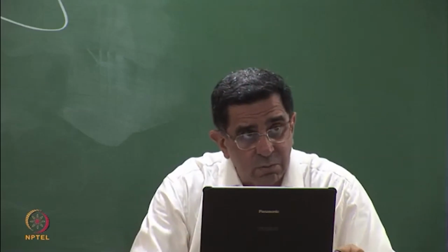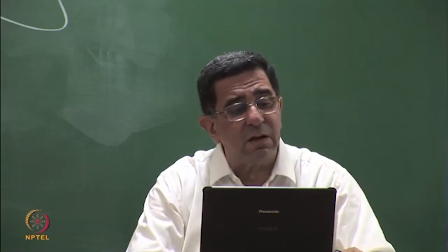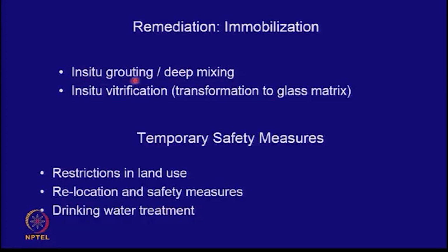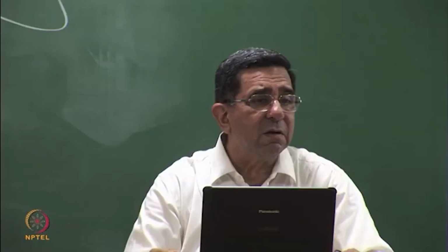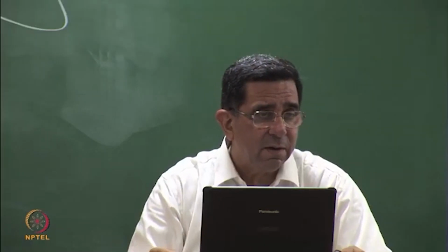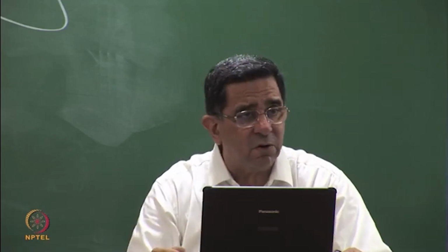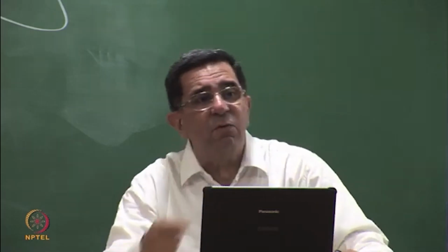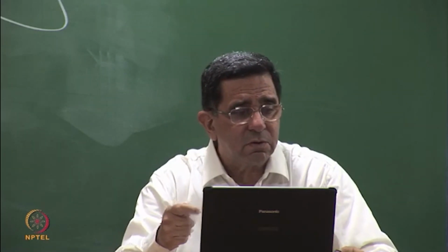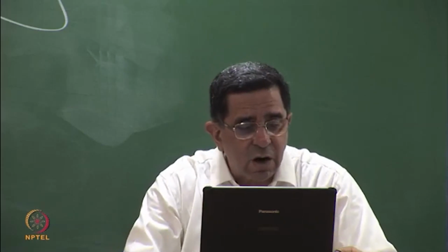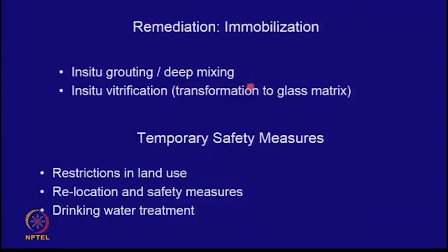If you continue with immobilization or transformation, another option is in situ grouting or deep mixing. You've got contaminated soil. Why don't you use the deep mixing technique using cement? If you can make a cemented matrix of the soil, at least the contaminant will not move forward. So in situ grouting or deep mixing is also an immobilization remediation technique.